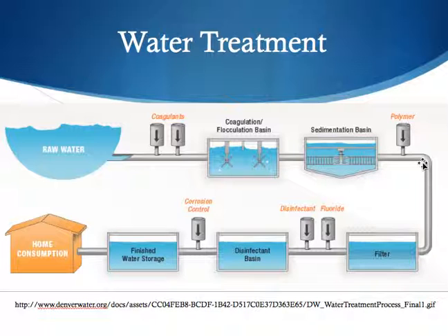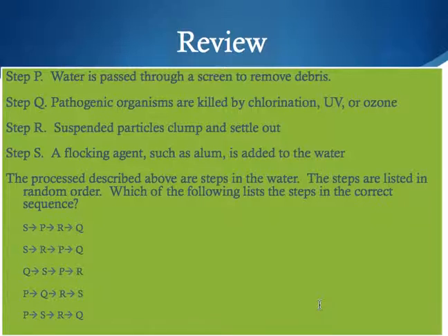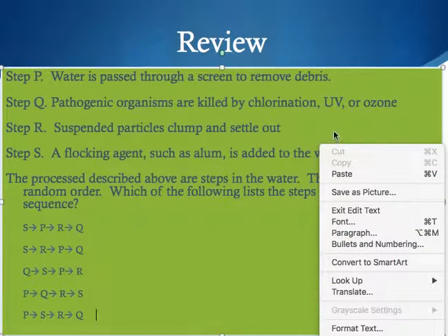This is the very first way we reduce turbidity significantly as soon as it comes into the water treatment plant. Next, it's going to go through a filter. It's usually sand. There may be some carbon in there to get rid of any smell, to filter out any dissolved material that hasn't already been taken care of by the alum.